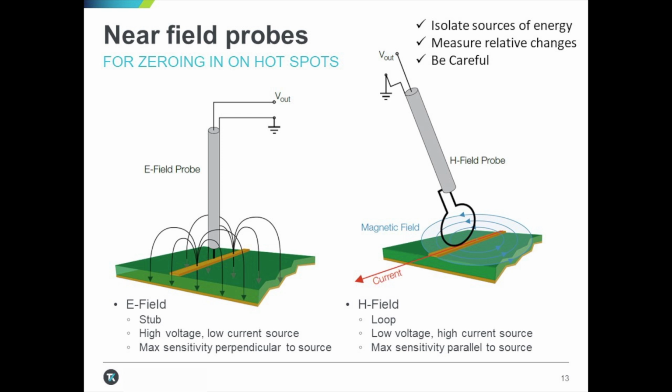Also, you don't necessarily have to actually buy probes. Near-field probes are fairly easy to make yourself, and there are many instructions that can be found online. What I will say, though, is please be careful when you are putting together your own probe. Remember that if it has a conductive surface and you are sniffing very close to the device under test or the PCB, you don't want to cause yourself any issues by shorting out the PCB during your test. Most, if not all, vendors' near-field probes are built with a protective non-conductive outer layer, which greatly reduces the chances of short-circuiting your PCB.